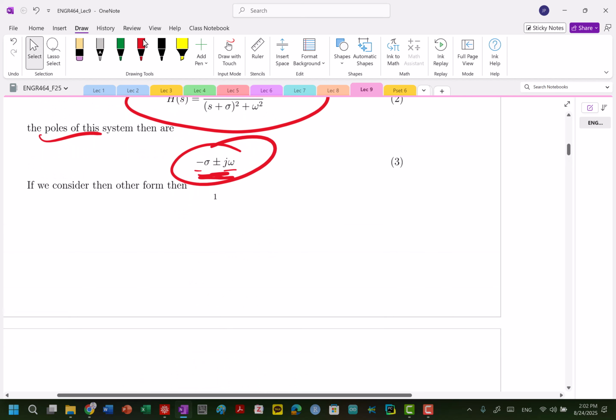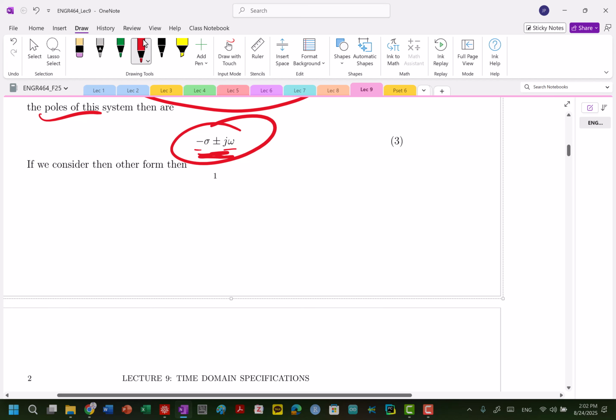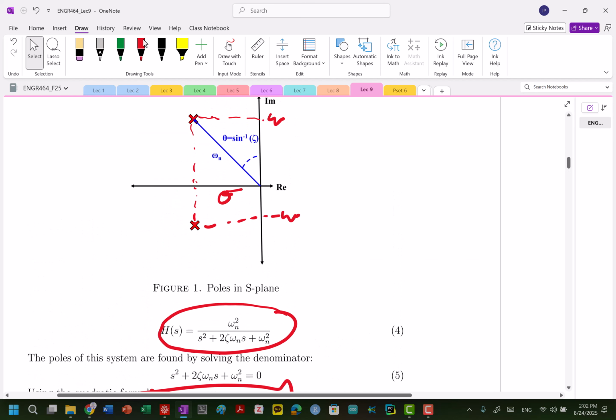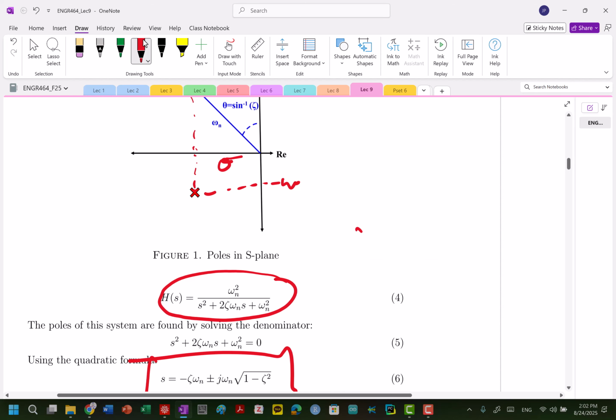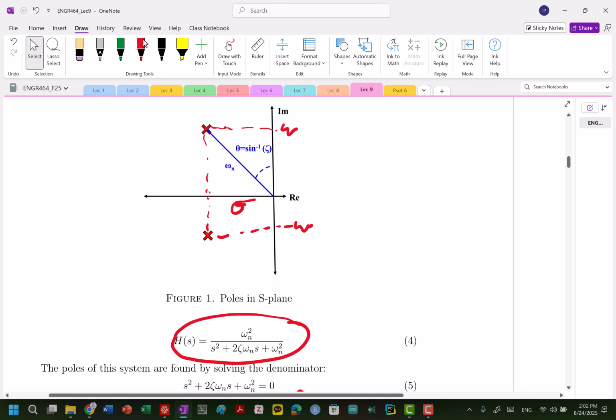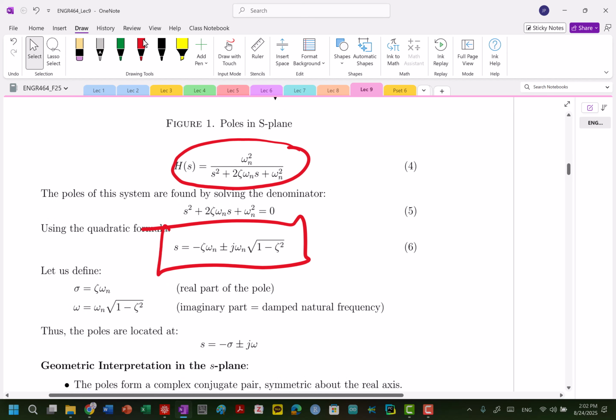I always think we can't just ignore this framework and this idea, but I want to now make the connection to the system we're more familiar with, where there's more of a physical connection, because we have the damping ratio and the natural frequency of our undamped system, which we can relate to our stiffness and the mass of our system as well. So this distance here is also omega, and we can do some math, actually, some geometry, to define some of these parameters.